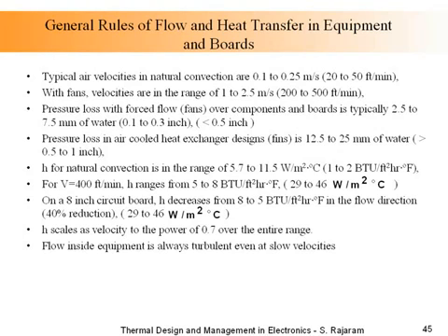So typically the value of H you will get inside equipment will be about 2 to 2.5 times that of what you will get by looking at a correlation over a flat plate. And the reason you get that factor of 2 is because of that extra turbulence and mixing that you're getting from flow going over those components. Okay?